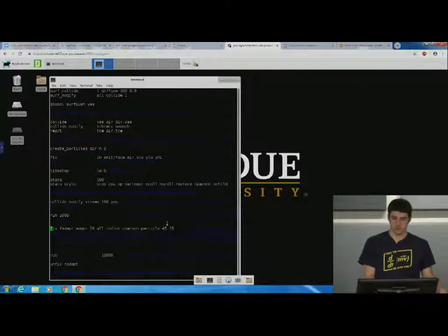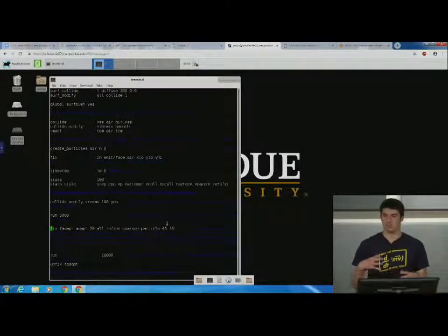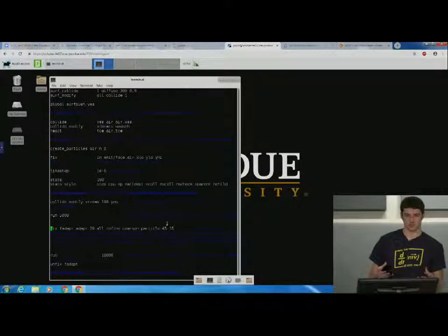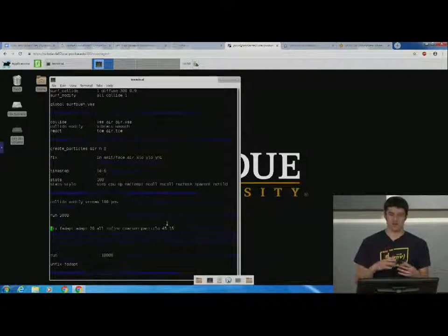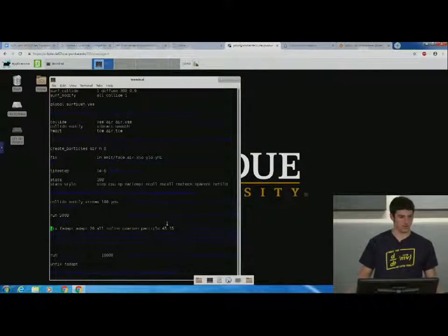If you have a hypersonic problem or something where your flow will vary drastically, like a ramp plume problem, so your density might be very large in one place and very small in another place, you want an adaptive grid. That makes your mesh finer in those places where the flow is very dense. In a hypersonic flow, you have a shock wave, so you want a lot of cells to really capture the shock. But behind your vehicle, you'll have a wake, so that's not as dense flow, and you probably aren't as interested in that realm.